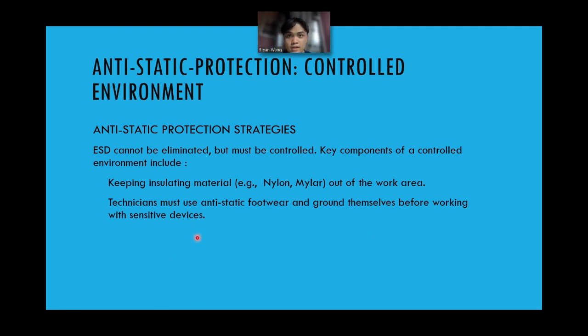Next, technicians must use anti-static footwear and ground themselves before working with sensitive devices. So this is one of the ways to control static in your working environment.